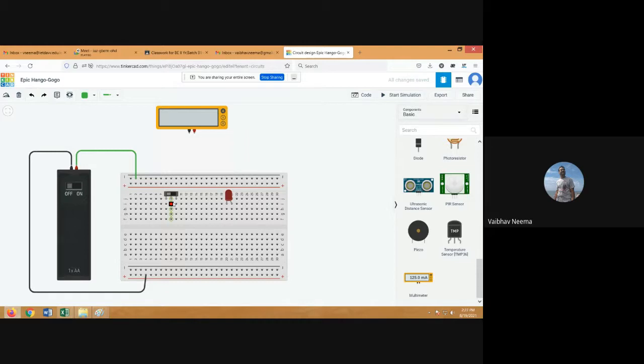When you click onto the common pin, you find that these dots are short circuited, which means you can select any of these connection nodes. Suppose I select the second one and put that connection with the supply voltage. So this middle leg of the switch we connect with the supply voltage. Supply voltage means 5 volts.